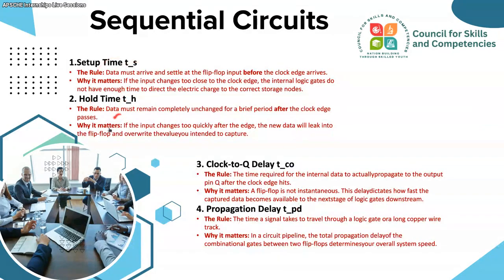Okay, so these are the certain rules for the setup time. Data must arrive and settle at the flip-flop input before the clock edge arrives. That is why it matters. And data must remain completely unchanged after the clock edge passes.